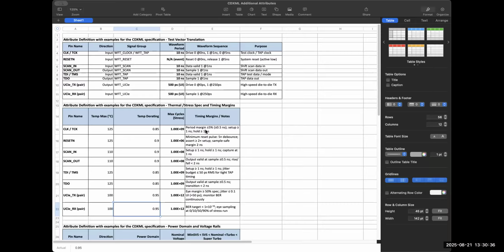And for your question, any pattern retargeting kind of flow will transform all that information by reading in the chip level netlist and finding out the chiplet pins and the appropriately connected chip pins, and it will automatically modify the pin names for the upper hierarchy, which will also propagate the signal group period and the waveform sequence. All those information can be handled by the translation tool.